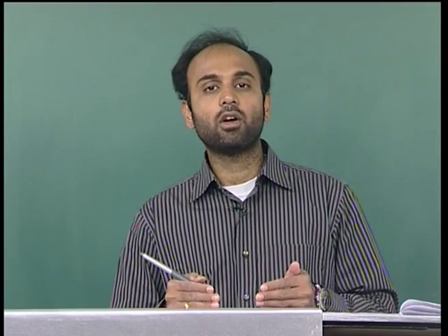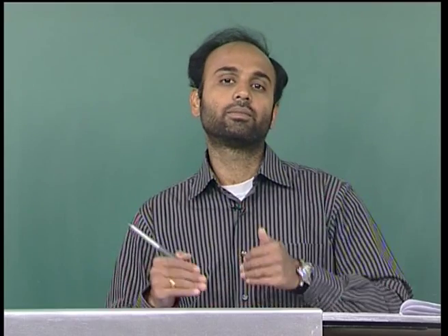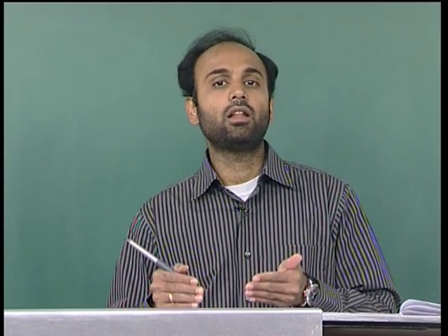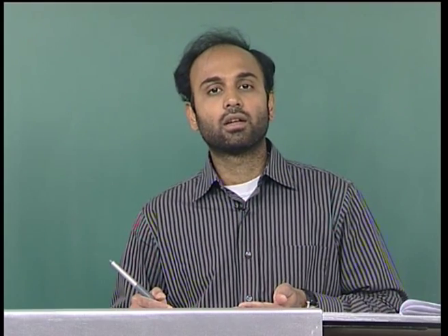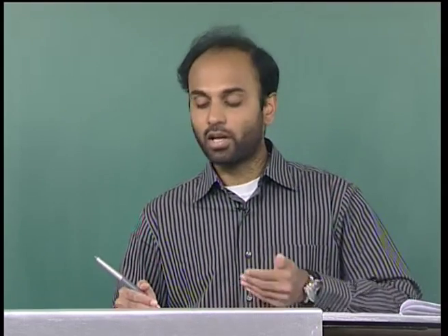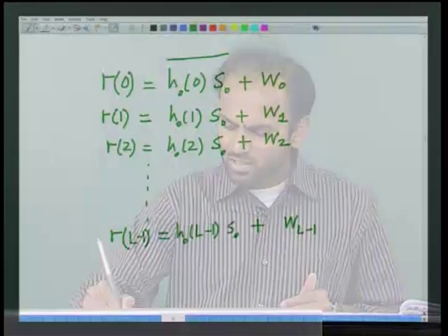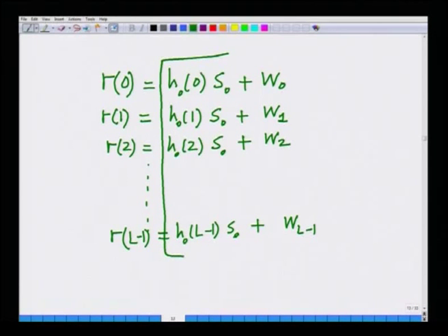This is after decorrelating with C 0 minus each delay. So there are L components, corresponding to the L decorrelations, and we have seen this before. This is fairly similar, in fact exactly similar, to what we have seen in the case of the rake receiver, except for these W's, which are now not simply noise, but noise plus interference. Otherwise this is exactly similar to the rake receiver.